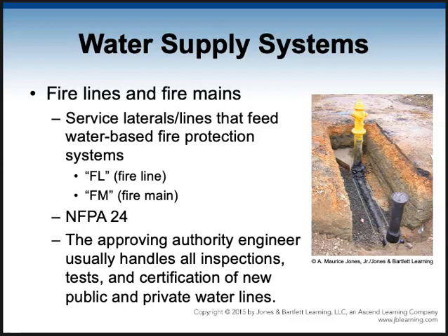So those fire mains are service laterals that then are going to feed water-based fire protection systems. So when, you might see the initials FL, that's fire line, or FM, fire main. A lot of times those initials will be used on the plans. All of this has to be done according to one of the NFPA standards. And we talked about the code's going to tell them they got to do it. The standard is going to tell them how to do it.